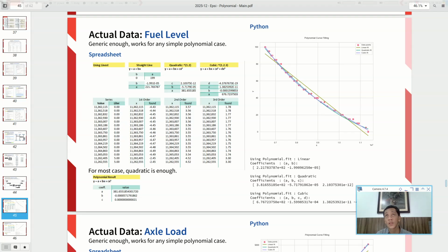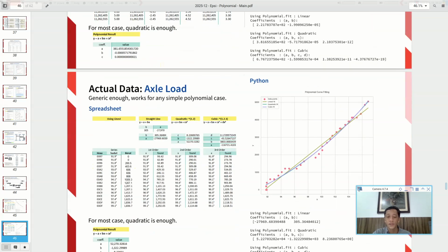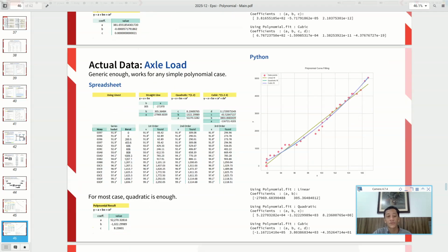The actual data that is needed is just start, middle, and end. So here is empty, full, and half full. Too many calibrations, over-calibration, is not good. But why do we have so much data? Because it's easier for the field operator this way. I don't need so much data. 7 is enough.